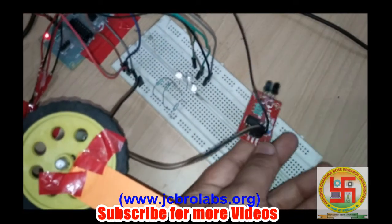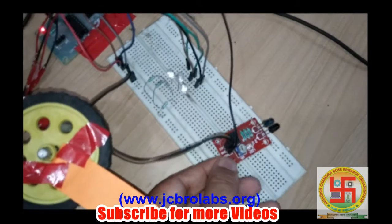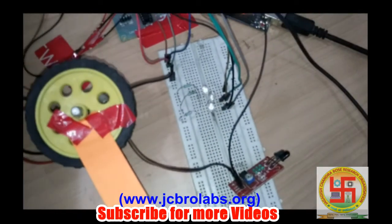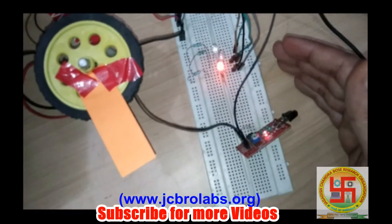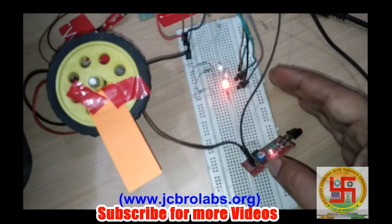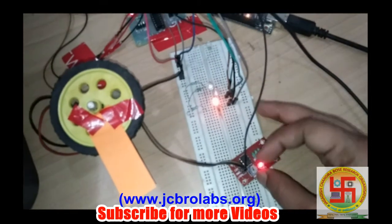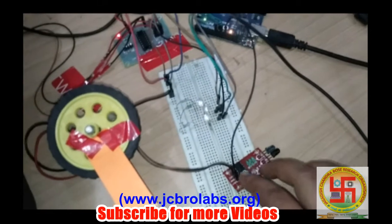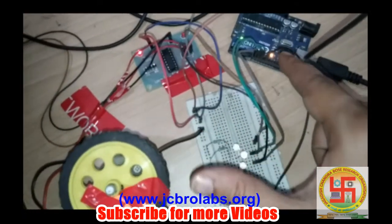Here is the IR sensor. If some obstacle is in front of it, it will give 1, and otherwise 0. So let's see, if this hand goes near it, it gives 1, and it indicates this by turning on this red LED. It has been powered with VCC and ground, and the output of this sensor goes to the Arduino pin number 12, this one.